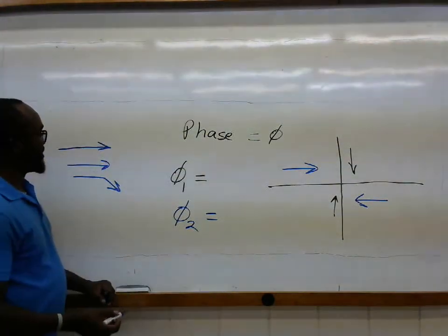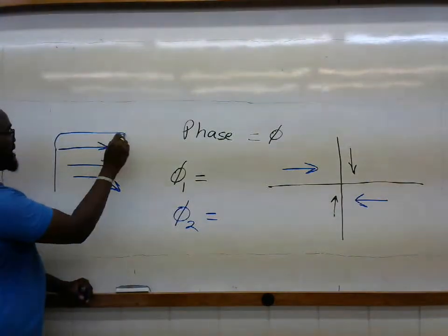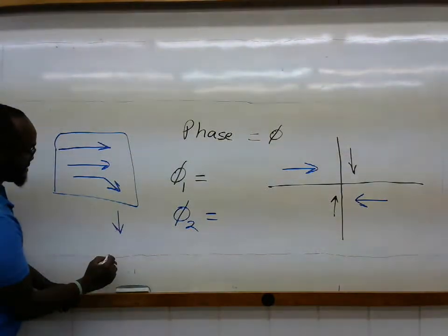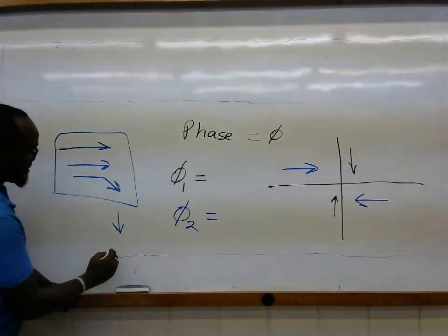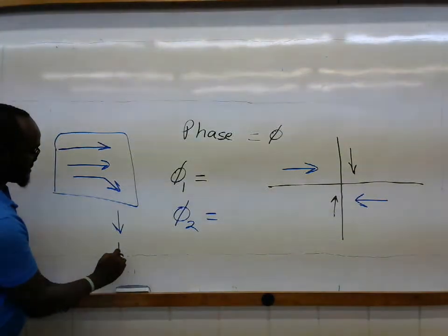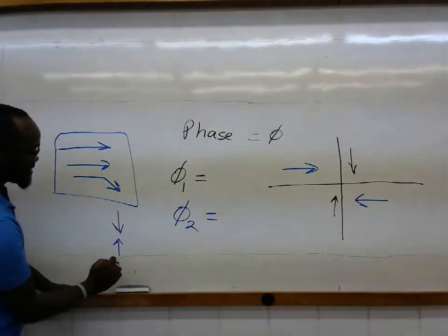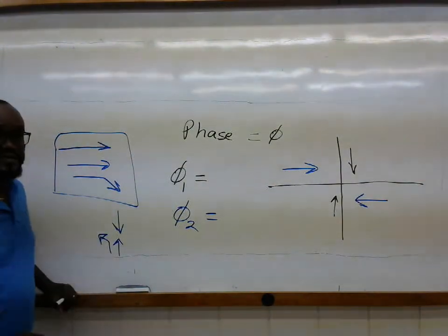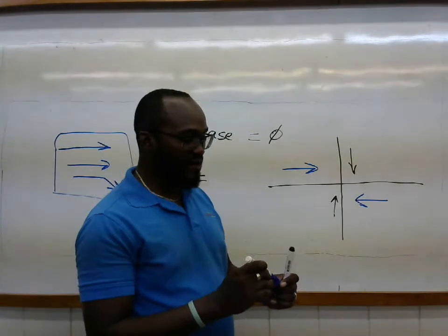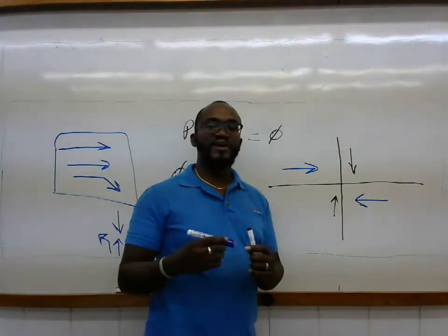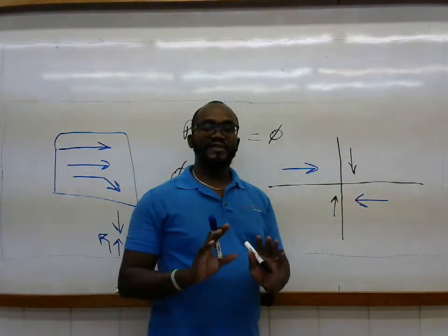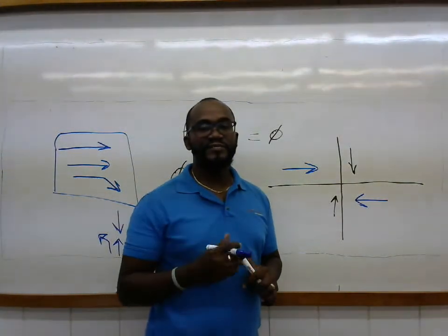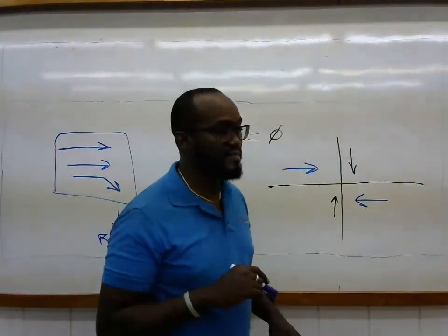In another phasing plan, you may actually see a southbound movement together with a through movement and a left movement with a signal phase, and so on. So phases can come in a number of combinations, but the important thing to remember is that a phase represents a group of concurrent movements that are given the right of way. The right of way is represented usually by a green symbol.